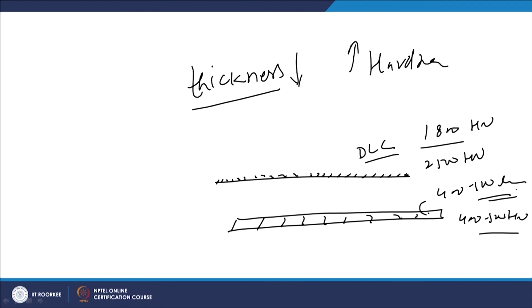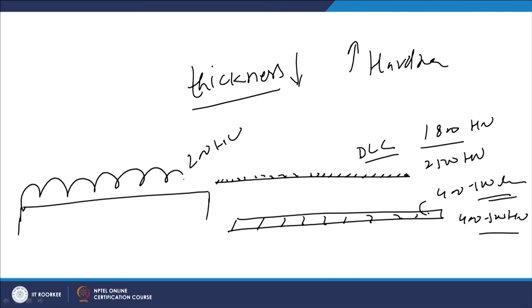And if the hardness is further lower, like austenitic stainless steel with a hardness of about 200 HV, then we can have a very thick layer in the form of claddings of austenitic stainless steel. So, the softer the material, the thicker the layers possible, while if the hardness is high, then we can develop thin layers for proper and prolonged performance of such layers for the surface.